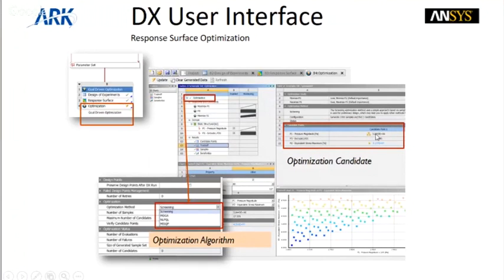You can see a three-star mark over here, and similarly a single star mark beside equivalent stress, and extrude is not having any mark. This indicates that it is the least concerned parameter with regard to that simulation. It is an unwanted parameter. We don't need to focus on the extrude depth of your 3D CAD geometry to optimize that design. It depends entirely on the magnitude of pressure which we apply for our simulation.